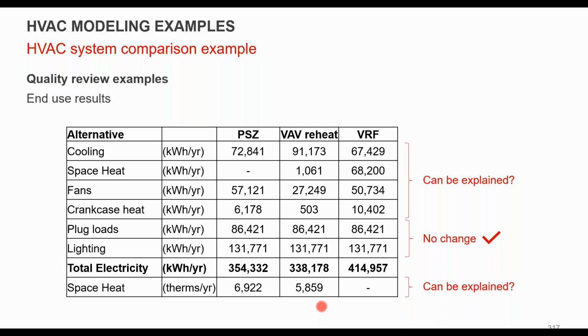Okay, there's a couple questions. One is about BTU per therm versus kilowatt. Yeah, and this is just an example of a condensing boiler option. I think certainly there's other reasons to go down that, but generally at lower water temperatures on a condensing boiler, you'll end up getting closer to 90-95% efficient delivery. So again, it depends if you have availability for gas as well, and what gas prices look like. So there could be a lot of reasons to go with condensing versus heat pumps or something else.